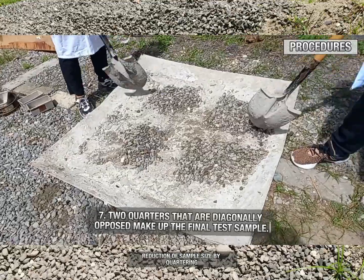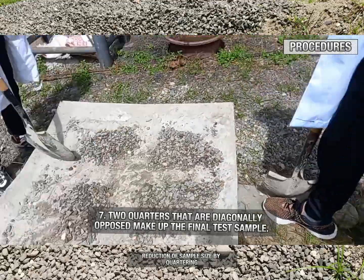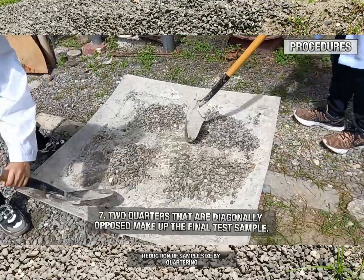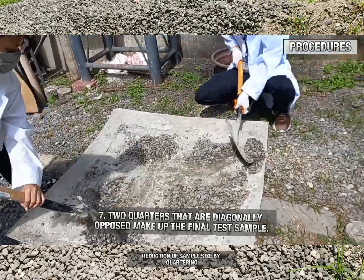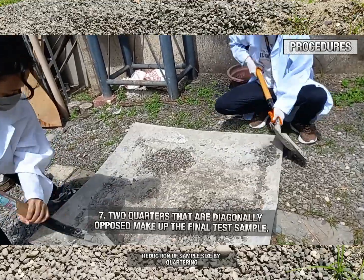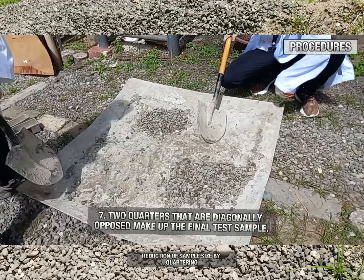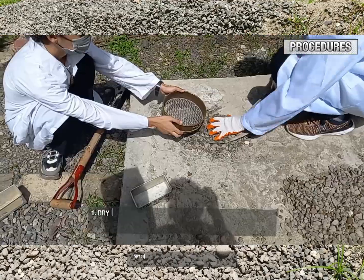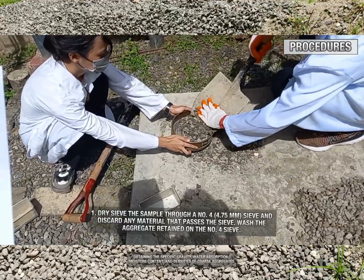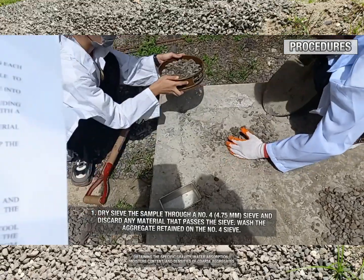Two quarters that are diagonally opposed make up the final test sample. Dry sieve the material through a number 4 sieve and discard any material that passes the sieve.